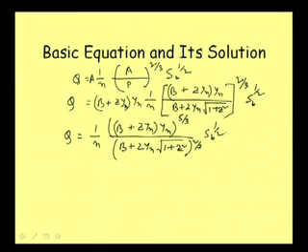Now, see in this expression, suppose we know the discharge. So, given the discharge, if we want to calculate y n, then we have a problem. We have a problem means we cannot separate out y n, because here we have y n as a product with this part, but here we have y n with this one as well as with this one.